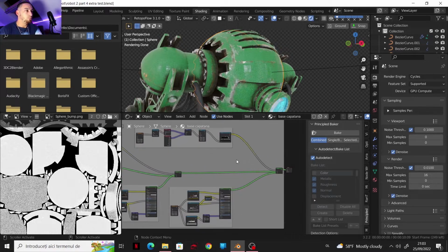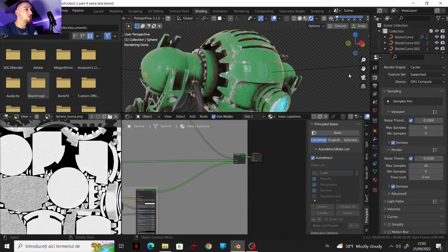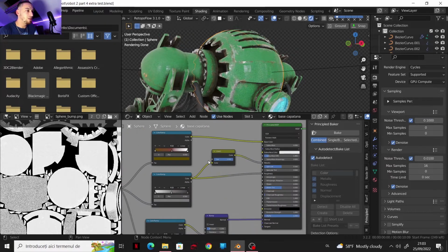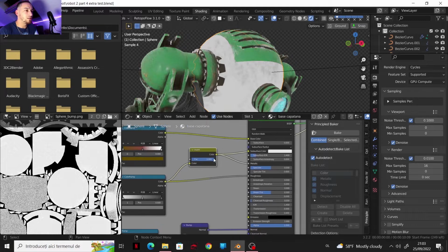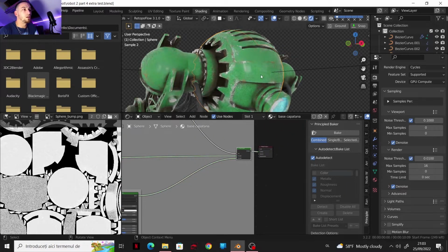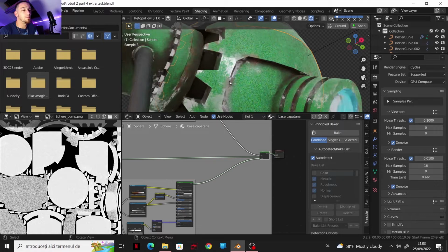Now it's pretty good, because it's a big problem with native Blender baking, as the metalness map is somehow hard to bake. You have to use an emitter or something like that to show up the metallic map. But let's say we are in this case where the metallic map is a little bit harder, because we cannot just take the only metallic part. You don't want to get this kind of a map, because it's gonna render the whole object metallic. So you need the metallic part only on these areas where the paint is scratched away. That's where this add-on is pretty good at baking the metallic map.